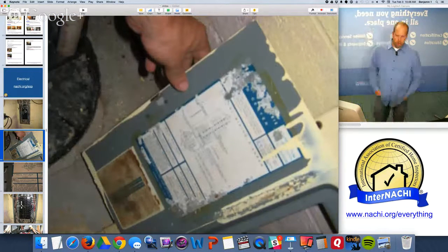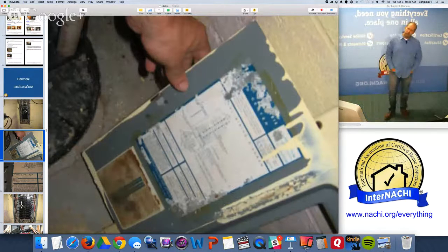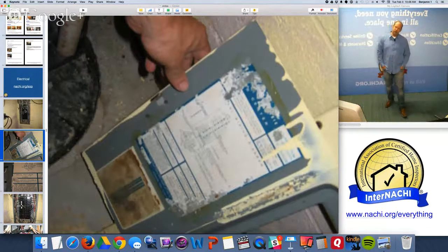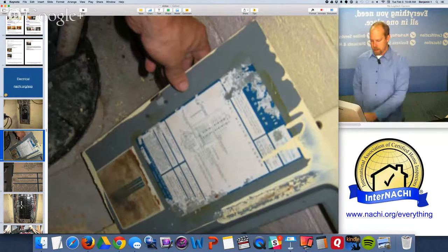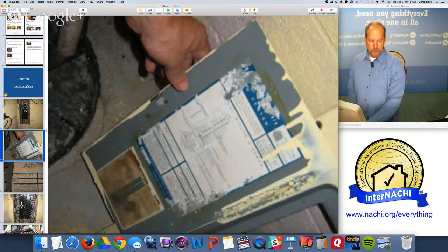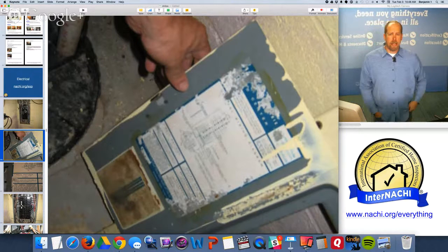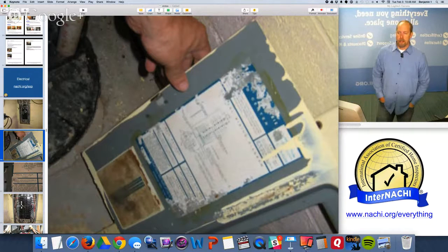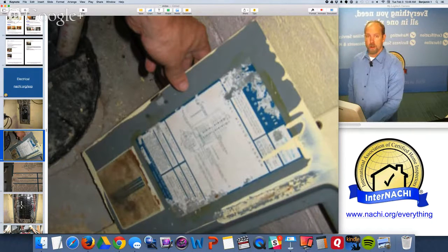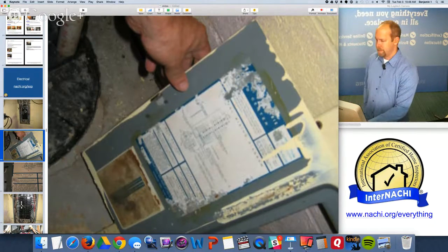I recommend taking a look at the identification of each breaker. Each breaker, each circuit should be uniquely identified. If it's not, that's a great way to recommend a licensed electrician to come to the property, inspect that defect, and look further prior to closing.